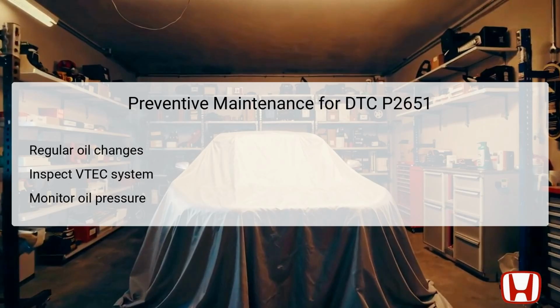To avoid encountering the P2651 trouble code in the future, adhere to a preventive maintenance schedule. Regular oil changes are crucial as they prevent the buildup of sludge and contaminants, ensuring optimal engine performance. Additionally, periodically inspect the VTEC system to ensure that all components are clean and functioning properly, preventing clogs that could disrupt oil flow.